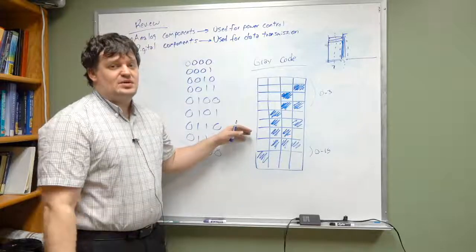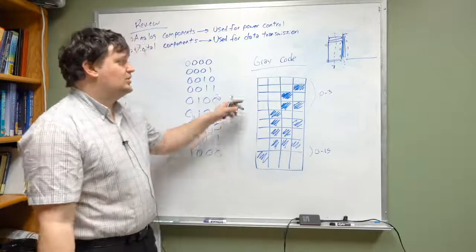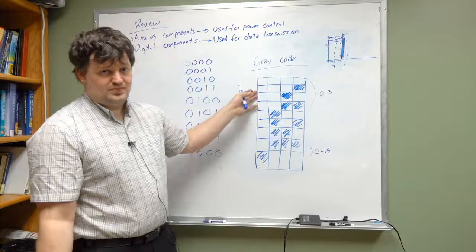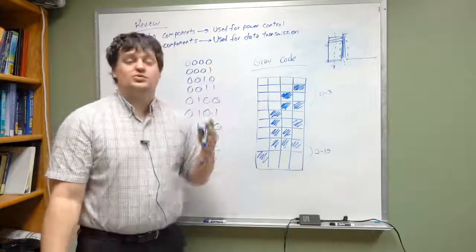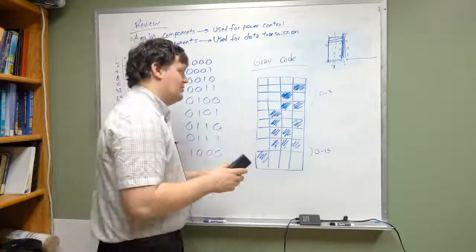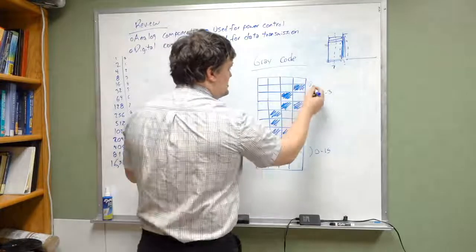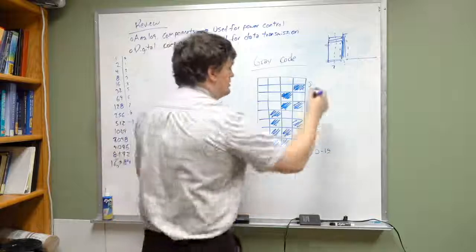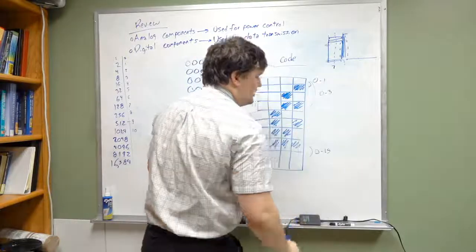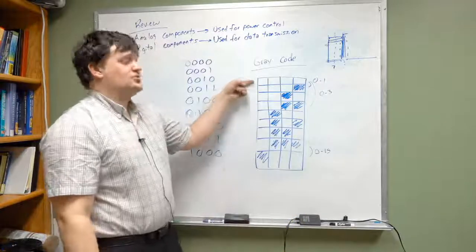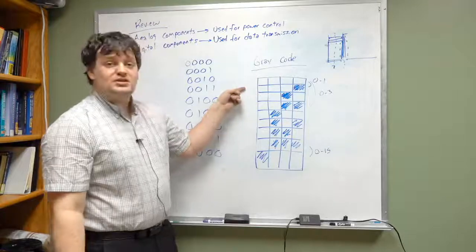If a time instance happens where it reads the value during a transition, you can guarantee it as one of two values. And I'll show you how. Okay, if a time error occurs in this transition here, it will either read a 0 or a 1. That's it. It will either read the value that it was, or it'll read the value that it's going to be.